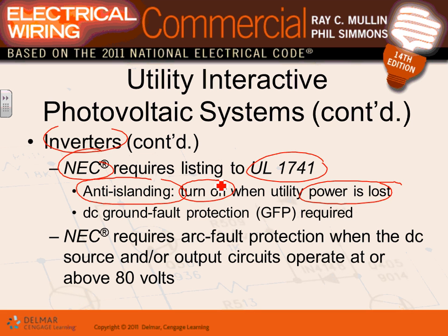They also require you to provide ground fault protection for your solar photovoltaic system. So you have a device that senses a ground fault, alarms that you have a ground fault, and disconnects the grounded faulted part of the system. Typically it's part of the inverter, guys. So if you have a ground fault anywhere, positive to ground or negative to ground, this device will sense it and interrupt it as well as alarm, because you don't want to create fire.